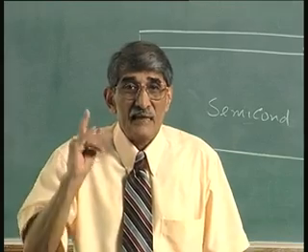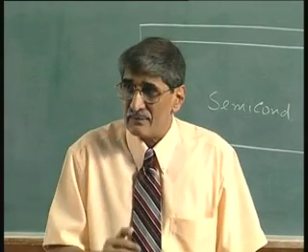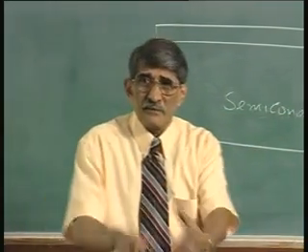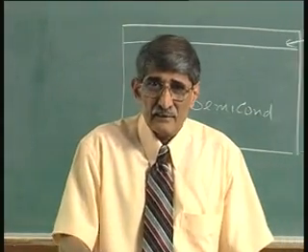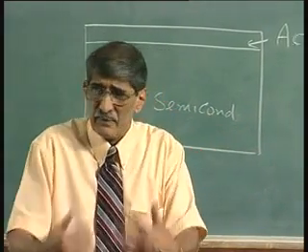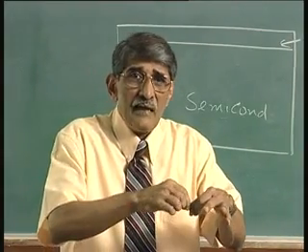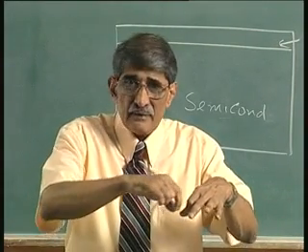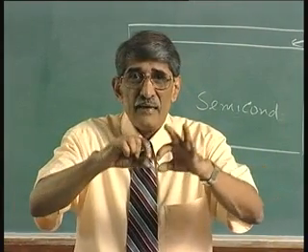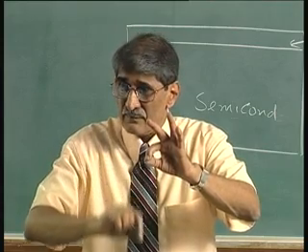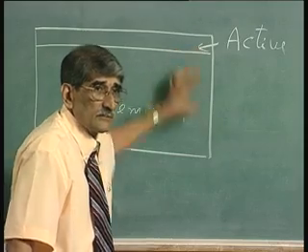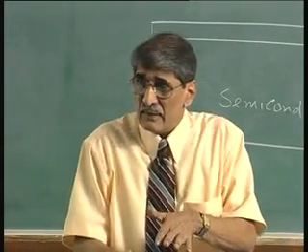So, that is why when you want to go to high speed, you want to cut down all capacitances. We have seen it right at the beginning. How to cut down the capacitance? Replace the entire bottom layer by an insulating layer, so that the junction capacitance, etc., can be reduced. We will see how it happens. Also, when you have a thick insulating layer and an interconnecting wire going from one device to another device, the capacitance of that layer with respect to the substrate can be reduced, because it can be made thick.